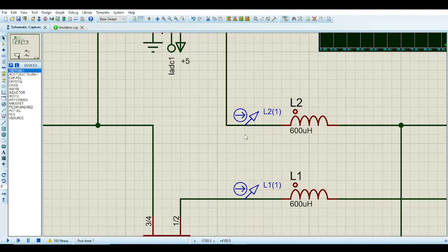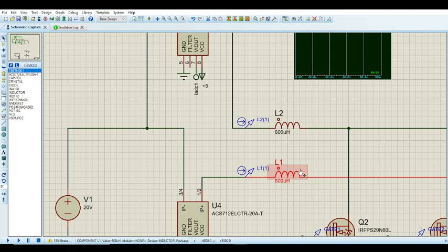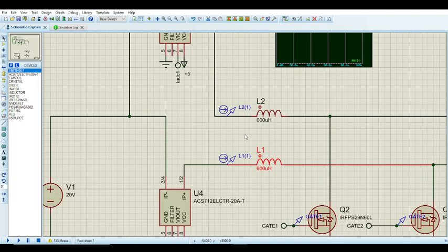And also keep in mind that for average current mode control, you have to operate in CCM. What that means is the inductor size has to be relatively large. So now it's 600 microhenries, because remember, you're trying to control the current through the inductor. Now you can if it's discontinuous, I guess you can, but it's much easier with CCM, if it's just continuous, right?